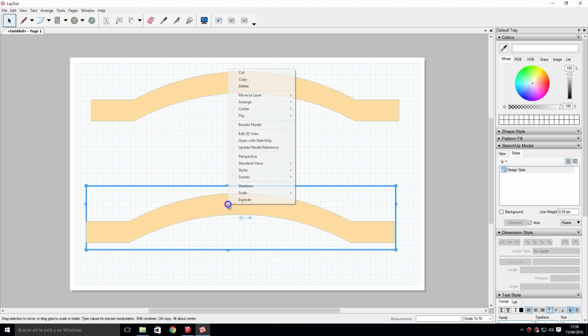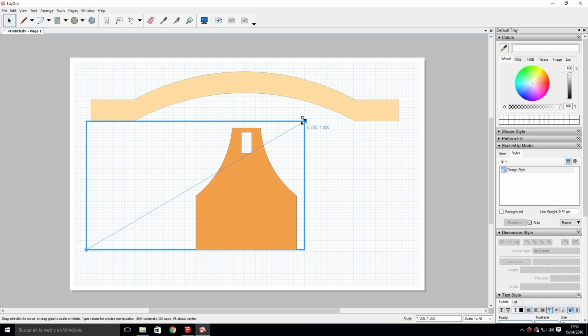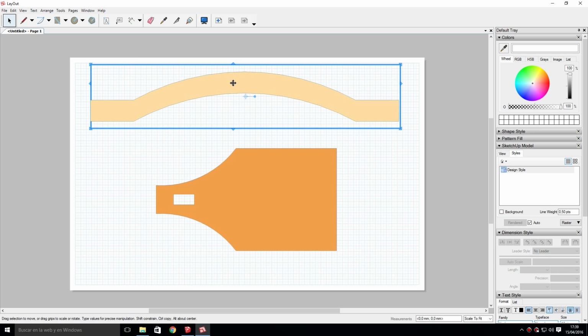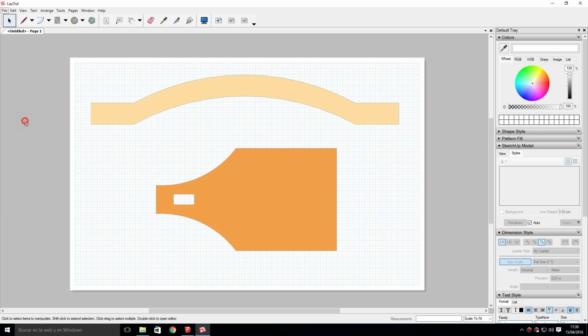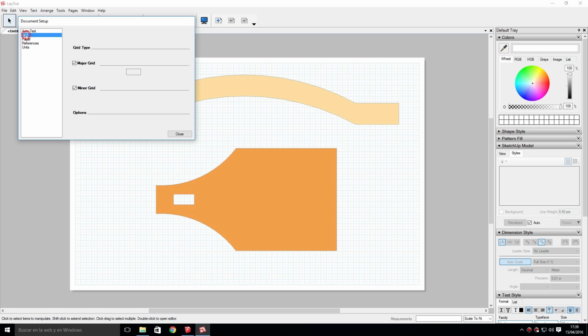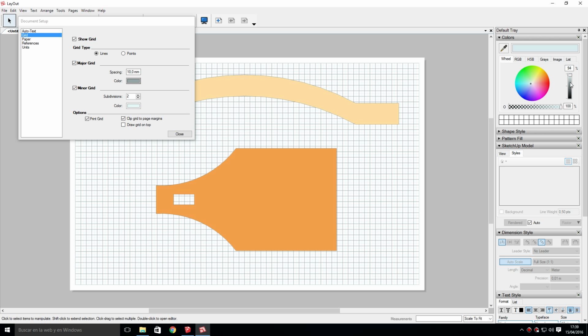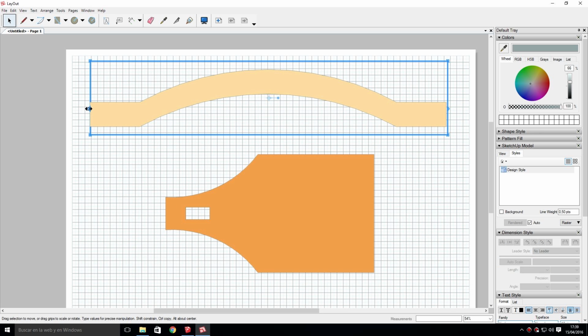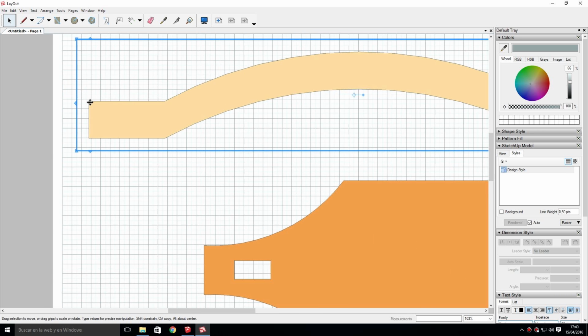Copy the viewport, select Other View. Go back to Document Setup and select Print Document Grid. The grid won't print if it is not checked. Here we can also select the color or spacing of the grid. Move it towards one of the lines so once printed it can be cut. It's easier if we set the snap off, go into Arrange, Grid Snap Off.